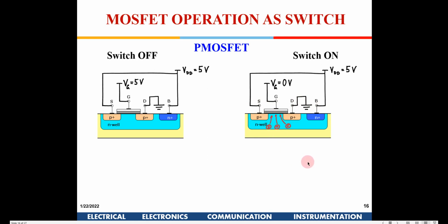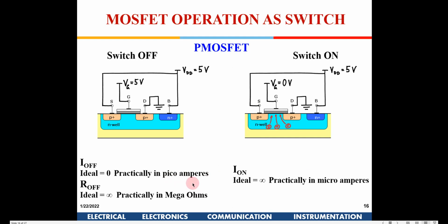So this is for the PMOS, it is exact. Now I off here also has to be practically 0, and also this is the N well. What is the significance of the N plus region? This is the N well, right? So this has to be lightly doped, because if you dope it high, then the Vt will increase, that we saw in the Vt equation. So the amount of doping has to be carefully chosen, as it has an effect on Vt.